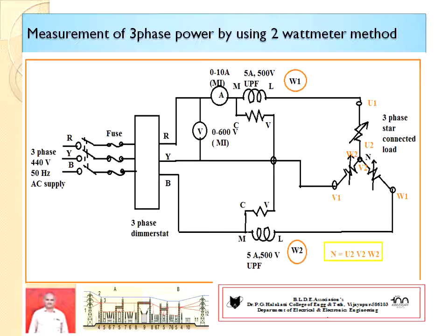In the star connected load, U2, V2 and W2 are connected to form a common point, because similar ends of the windings are joined. U1 is the starting end and U2 is the finishing end. All finishing ends of the windings are joined to form a common point or star point, also referred to as the neutral point. Then U1, V1, W1 are taken for further connections.